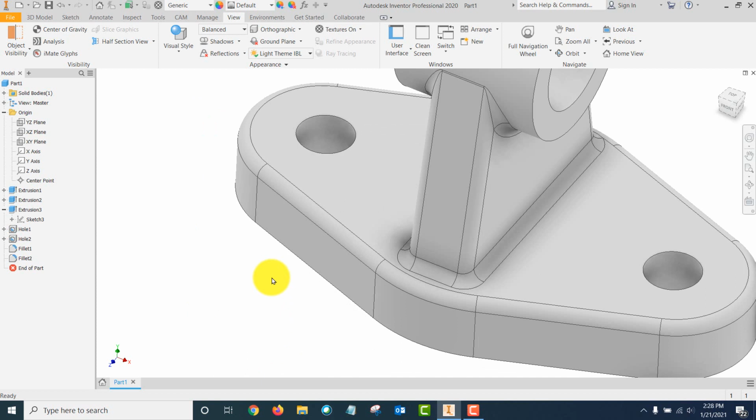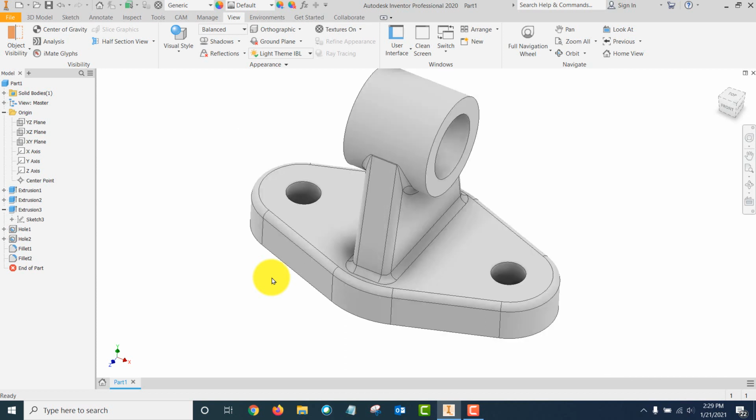Now, when you're turning these in, at this point, I really don't care either way. When we start generating drawings, we usually do not show the tangent with the edges unless the tangent part is not showing up in our drawings. And we have some that are kind of weird like that.